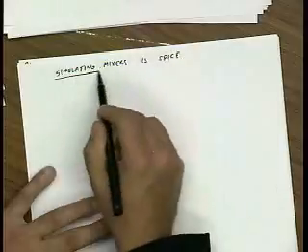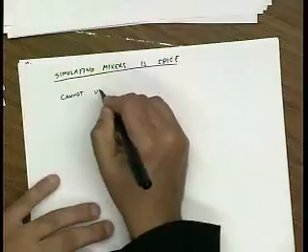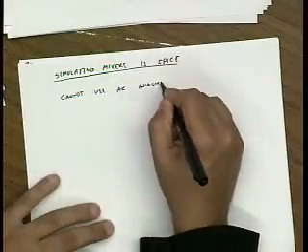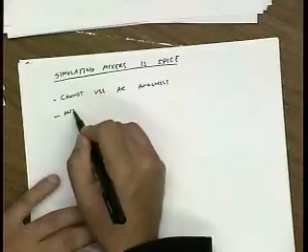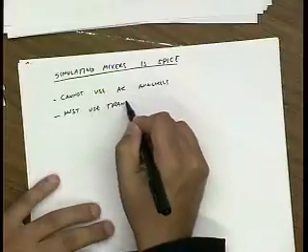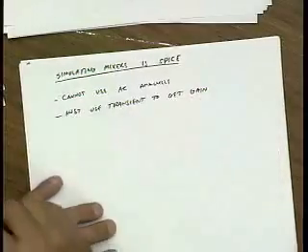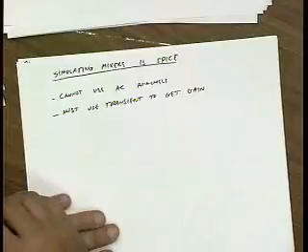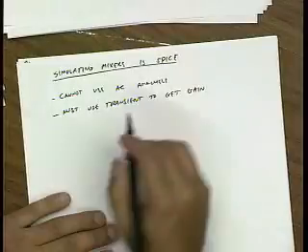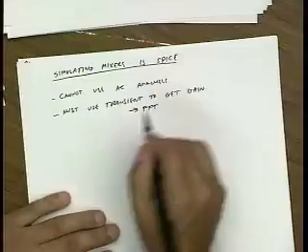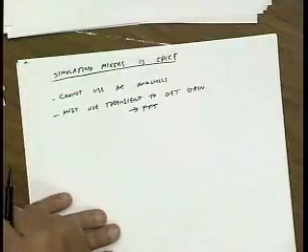And if you're using standard SPICE, you know that it's really difficult to simulate mixers. First of all, because mixers are time-varying circuits, you can't use AC analysis, right? So we cannot use AC analysis. That means you must use transient to get the gain. Even just to get the gain of a circuit, you have to do a transient simulation. Then you have to follow it with an FFT to be able to discriminate the different frequencies at your output.